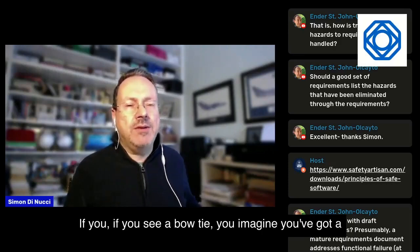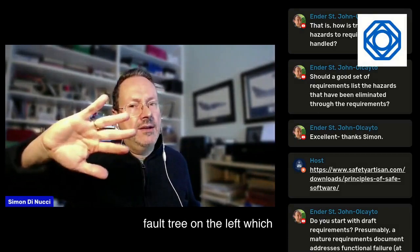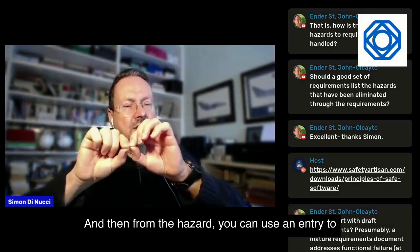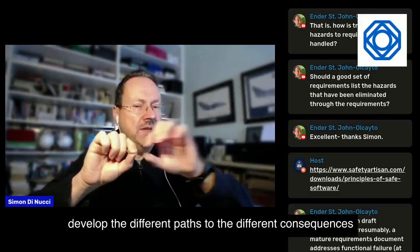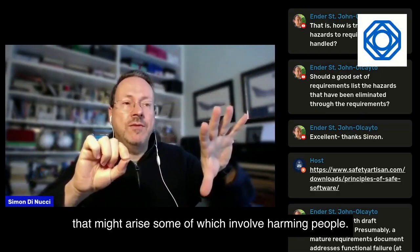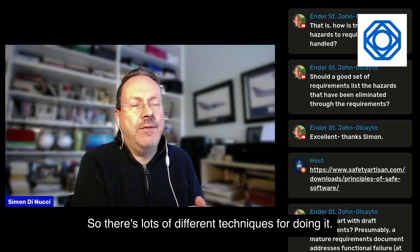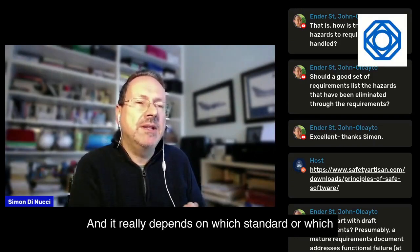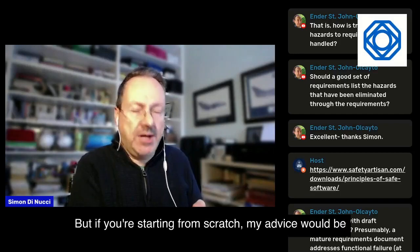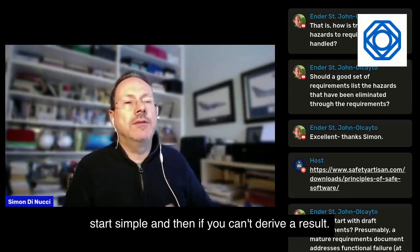If you see a bow tie, you imagine you've got a fault tree on the left, which focuses you down to the hazard, and then from the hazard you can use an event tree to develop the different paths to the different consequences that might arise, some of which involve harming people. So there are lots of different techniques for doing it, and it really depends on which standard or which industry you're in.